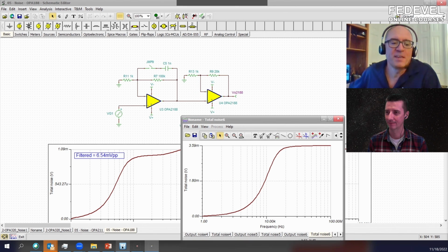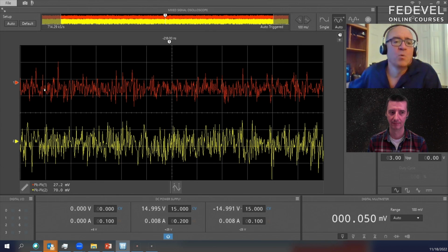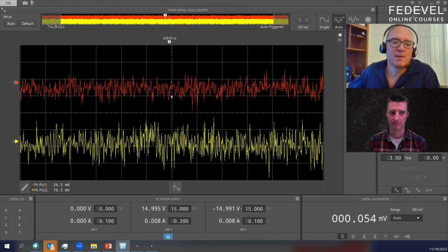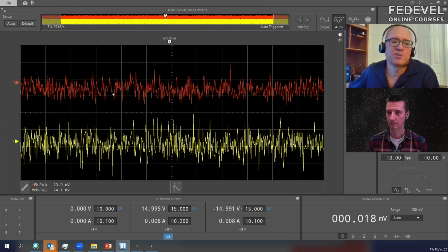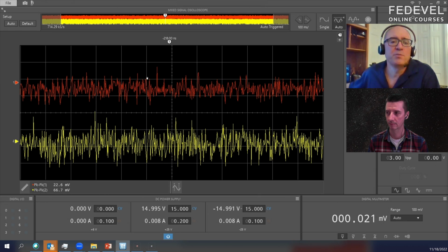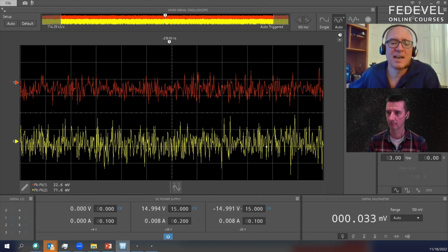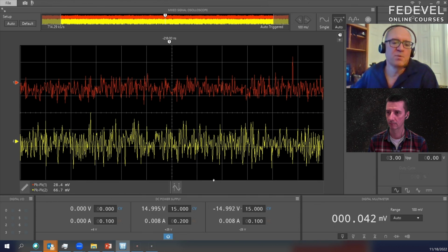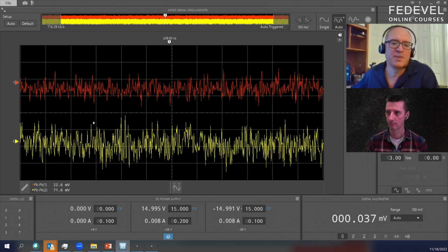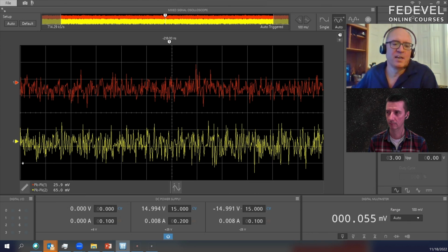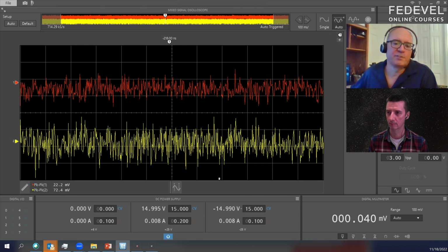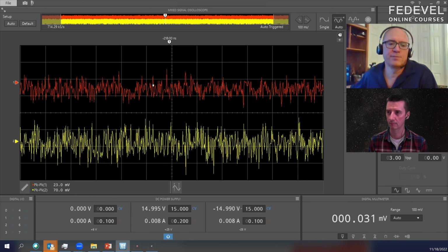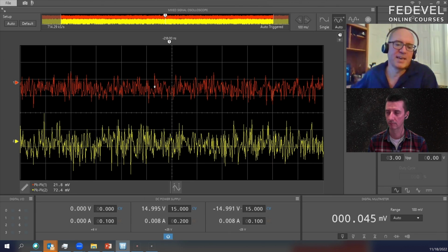But you know, one thing about this I should mention, it's an excellent instrument, but and this applies to really any oscilloscope, when you're measuring the peak-to-peak value, it's not really the same as getting the RMS, which is essentially the standard deviation of the signal. And so you'll get a few spikes that will be outside that region, and that's going to give you a little bit of a different answer here. In fact, with intrinsic noise, the more points you collect, the higher the peak-to-peak is going to be, because it's a Gaussian distribution, and the more points you collect, the more likely it is you're going to be on the tails of that distribution. So the best way to analyze this noise values is to look at the standard deviation. And we'll see that in the next demo.